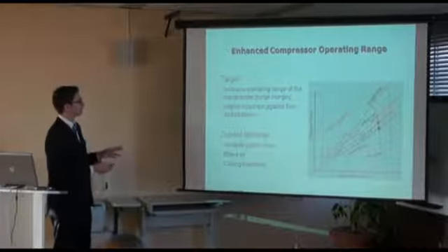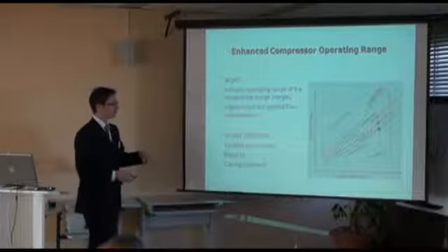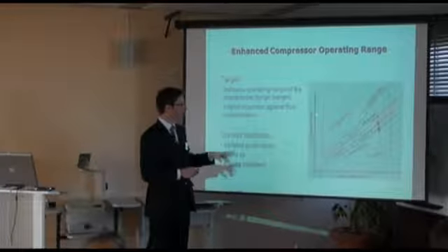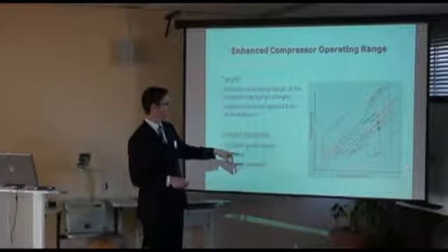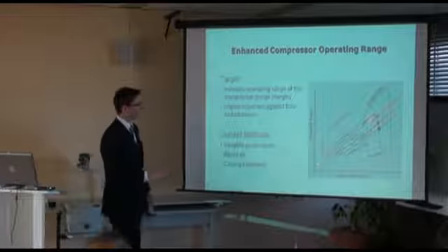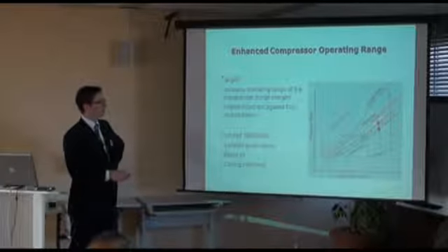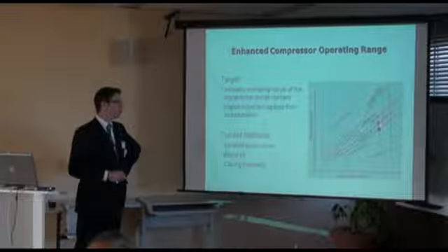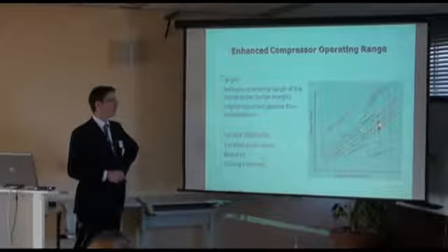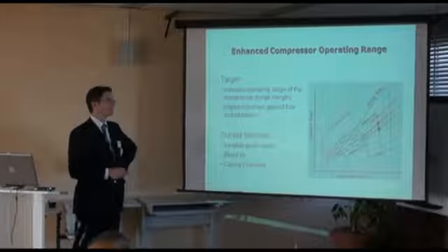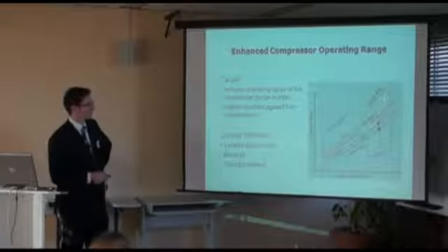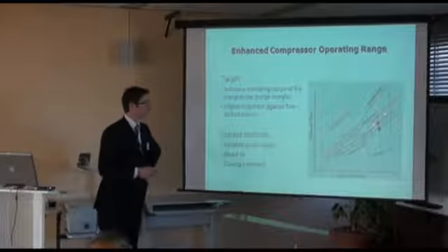You can imagine that turning a flow in a direction where the pressure is higher is very difficult to do. So, just briefly explaining the topic here on the compressor map. We've got pressure ratio over flow and an operating line together with the operating point here. When you move this operating point towards higher pressure ratio, there's a stability limit, which is called the surge line or stability line.